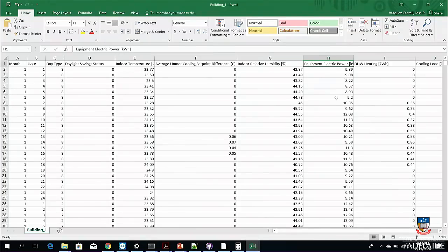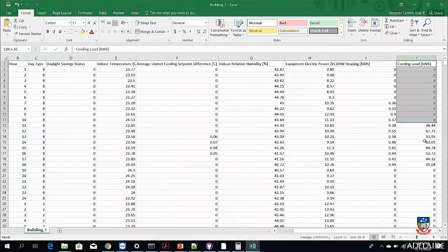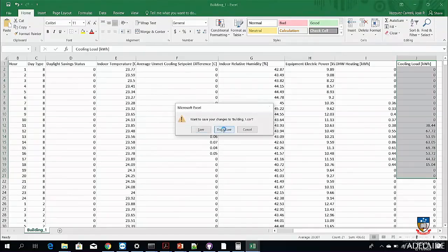So some of these buildings will be residential. So I took real world data and fed the simulations with it. And some other buildings, especially the office building, will not really be real world data, but it's just simulated. But I added some random noise to it. And then some of the buildings will have domestic hot water use, and then all the cooling loads that I simulated. That also includes the thermal heat gains of the appliances inside of the building that have an impact on the cooling load. So there is one file of this per every building.